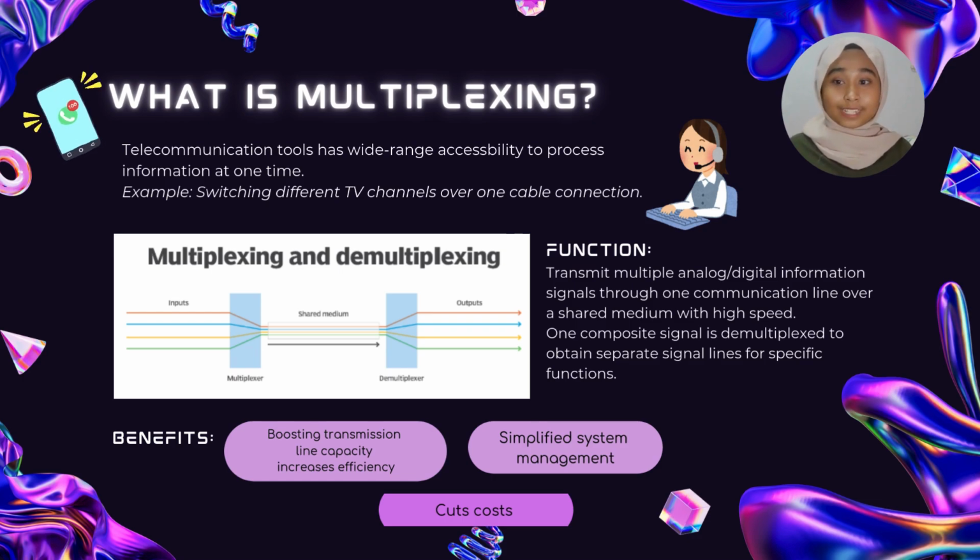Okay, now we'll look at the study of what is multiplexing, or muxing, which contributes to today's wide range accessibility of telecom tools when transmitting and receiving information at one time. So, for example, the ability to switch through different TV channels through one main cable connection is due to multiplexing. It's devised to transmit multiple information signals, analog or digital, through one high speed communication line over a shared medium.